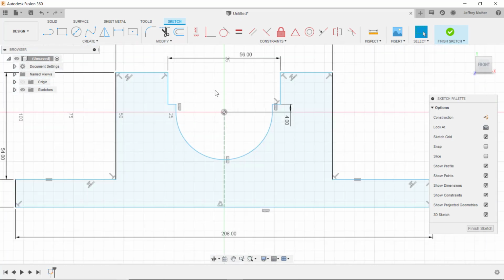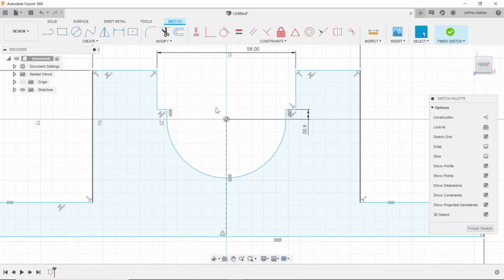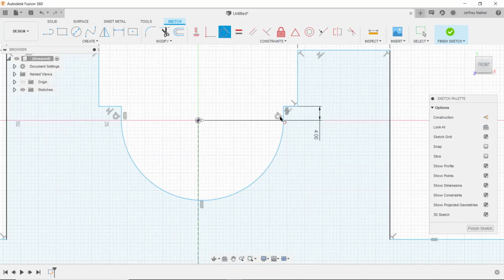Now when I did that, I lost a constraint someplace. I believe the collinear between here and here, so I'll do the collinear, put that back in between here and here, and I see a bunch of my geometry. I lost the dimension on this, and again, if you're not sure, start dragging geometry, and actually I can see several things. So I lost the tangent over here, so in my trimming I have to be careful that I can lose some constraints that I wanted to have.